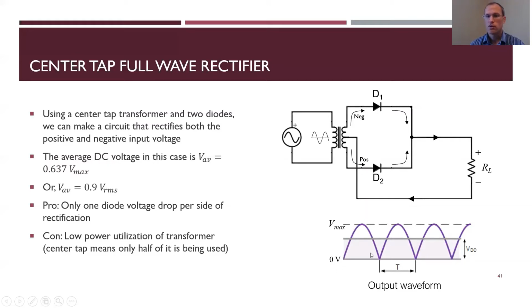The input on the secondary side is now like this. You don't have those negative parts anymore because this diode is taking care of it, but you still have that threshold voltage being cut off. But you end up with a lot more parts where you're actually getting power, as opposed to sitting in zero land for half a wave. This is called a full wave rectifier because you actually get power almost the entire time.